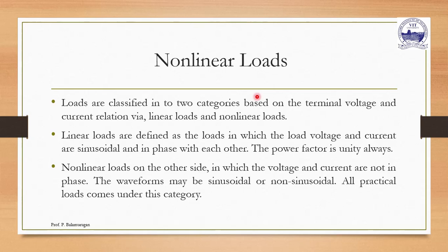Ideally, both voltage and current must be in phase and the power factor of the system must be unity. This is the definition of a linear load under ideal conditions. A nonlinear load, on the other side, is one in which the system voltage and current are not in phase and the waveforms may be sinusoidal or non-sinusoidal. All electronic loads and practical loads fall under this category.